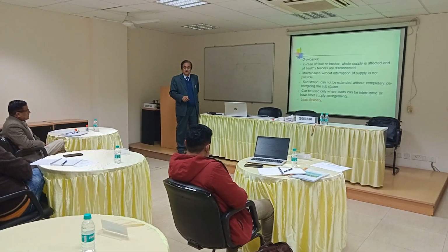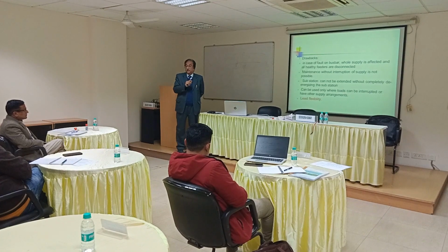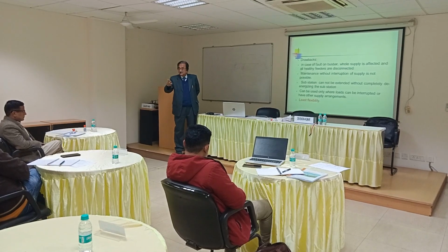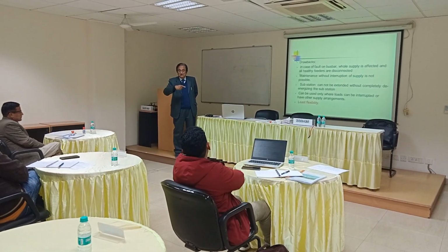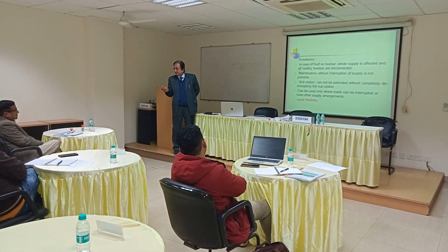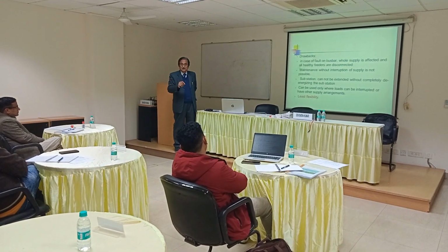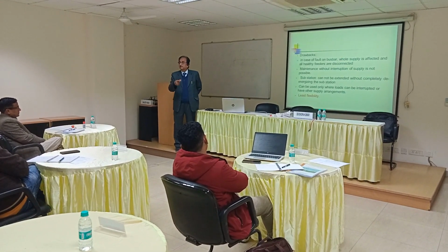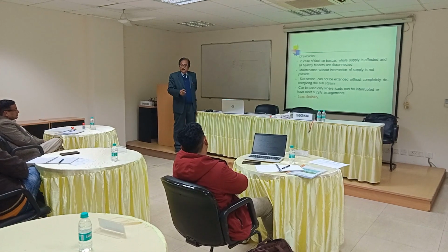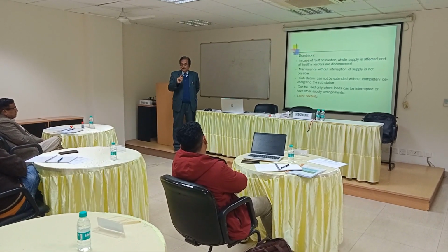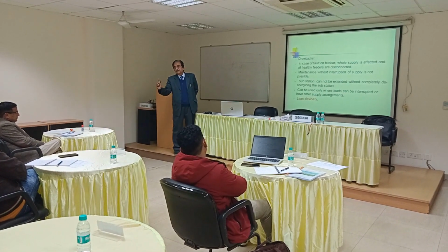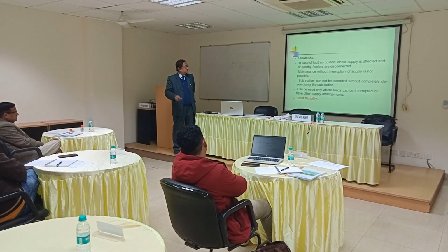But the drawbacks are that in case of any fault on the bus, the complete system of that voltage level will be dark, because we don't have any other arrangement. So that particular voltage level will not work, and if it is the higher voltage level, it means the total substation will be dark. And if we are to maintain the bus, we have to put the bus under shutdown, and it means the complete substation will be out.